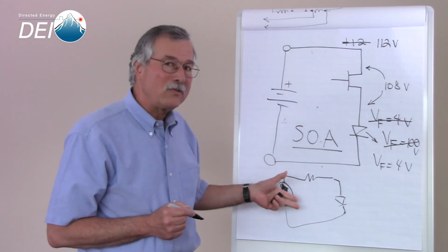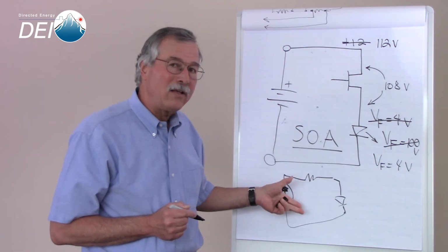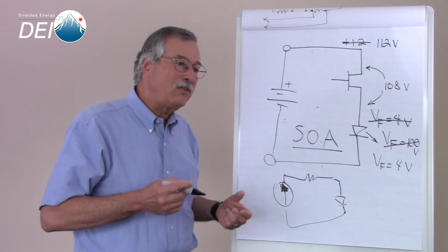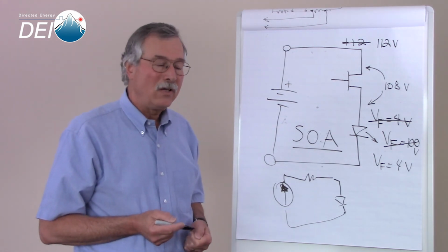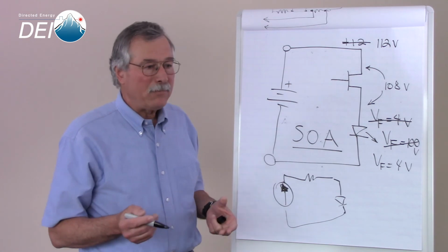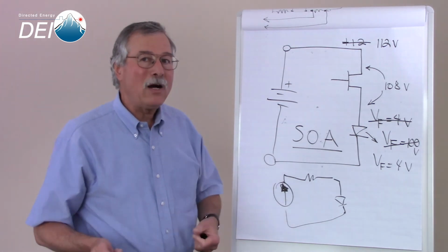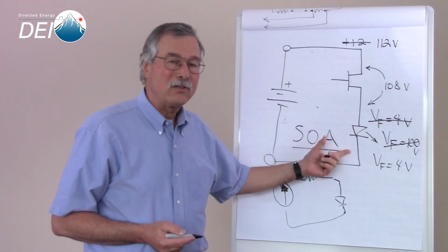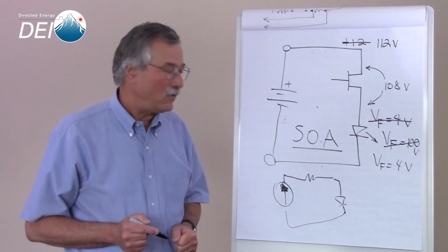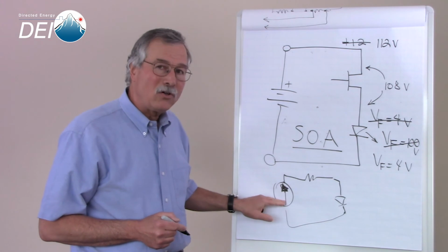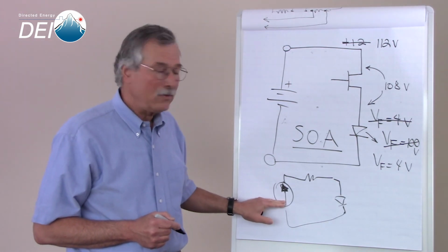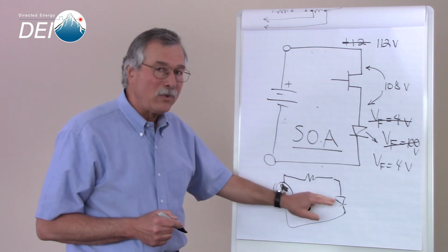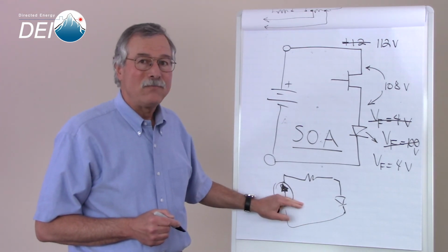Sometimes when customers look at a piece of strip line, they will think that perhaps we're trying to match impedances and that this is an RF sort of business. We use strip line because we are trying to get maximum power transferred between the laser diode driver and the laser diode. This is not the case. A current source has a high output impedance. A laser diode has a low impedance. We never will get these devices matched.